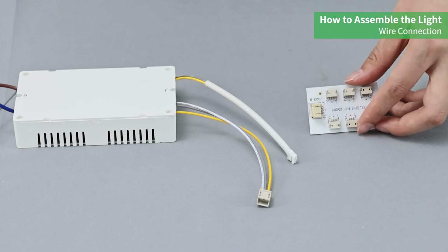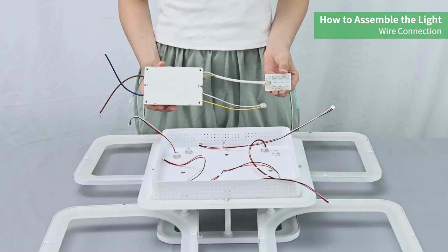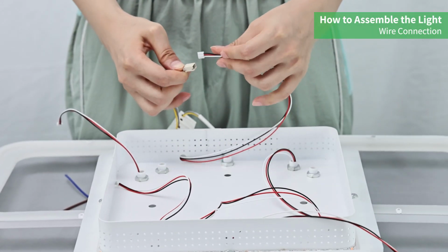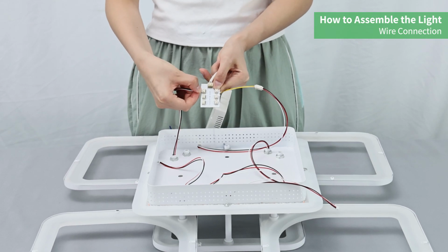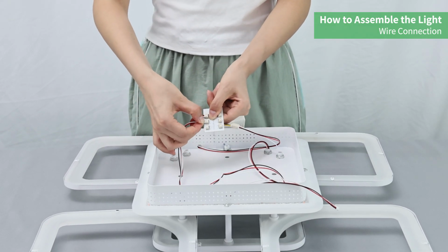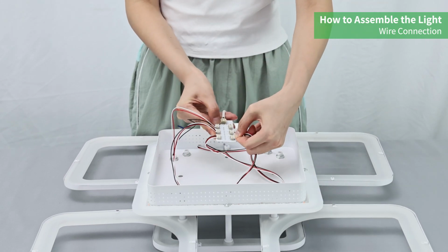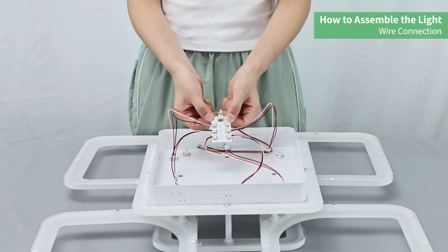Wire connection. Insert the main wire of the adapter into the largest port of the collector. Next, connect the other wire of the adapter to the wire from the light base. Connect the wires of each square light head to the collector. Tip: the wires can be inserted into any port on the collector. Ensure all wire connections are secured to avoid looseness. Check all nuts and screws to ensure the fixture is securely installed.